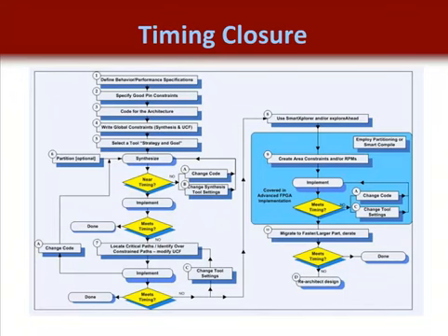Step 5 is to choose a synthesis strategy and goal. We will talk about what that means a little later, but for now you should understand that this choice will direct XST to synthesize your design in a pre-optimized fashion using recommended synthesis options. This makes it easy for a Xilinx designer to get their design synthesized easily. However, most experienced designers would rather go ahead and have the knowledge to customize the options as they choose. So we're about to go into that in this module.